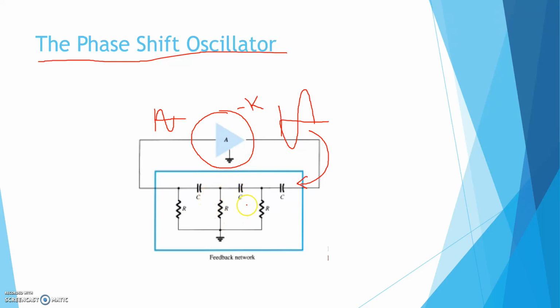To make a 180-degree phase shift by a feedback network, obviously an inductor or capacitor should be a component of that feedback network, because if the feedback network is purely resistive, we cannot get any phase shift between input and output. We know this from the basic concept in electronics. So if the basic amplifier block is an inverting amplifier, then we have to make the feedback network with the help of capacitor, inductor and resistor.